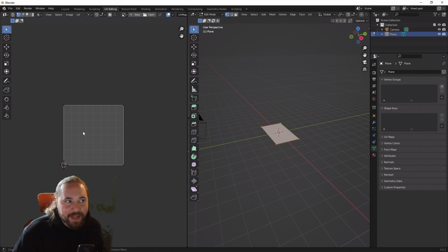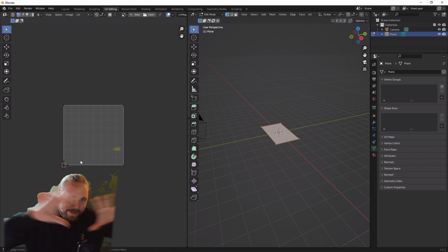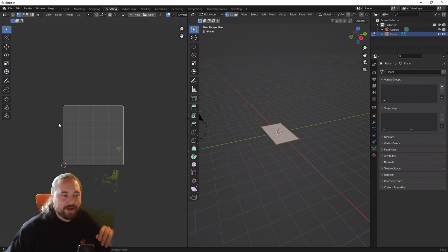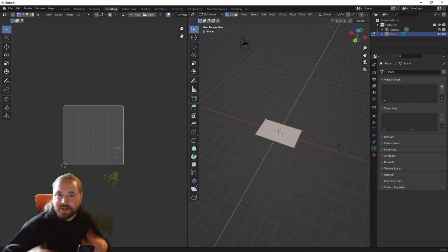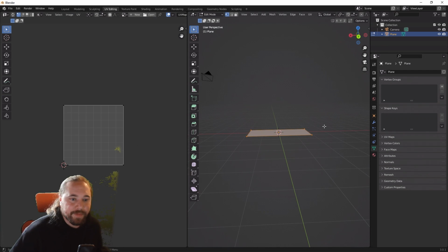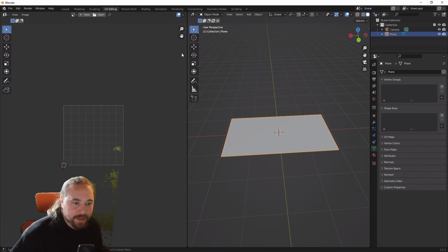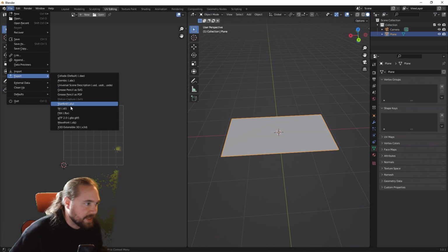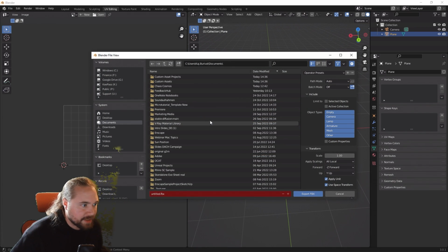If you're thinking about the UV textures, this is now still a square, the 2D texture information, but the video that you're going to apply will be squeezed to the scale anyways and then stretched again, so it's going to fit. We're just going to take it as it is, a simple plane, have it selected, export as FBX.